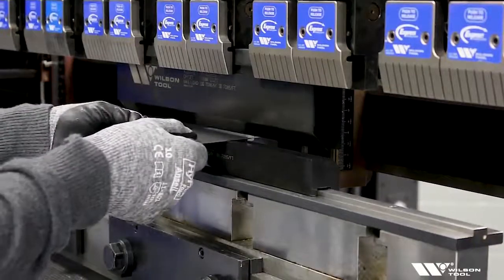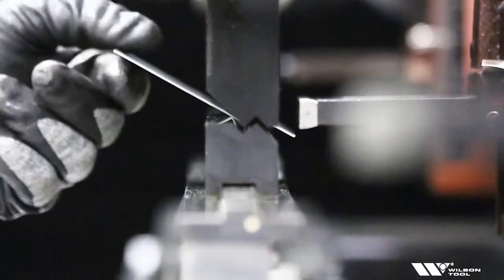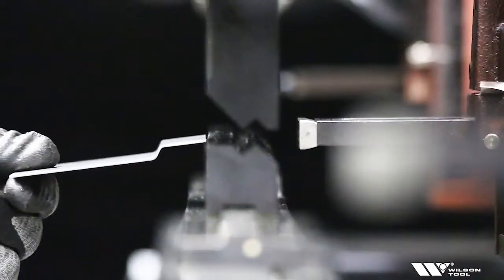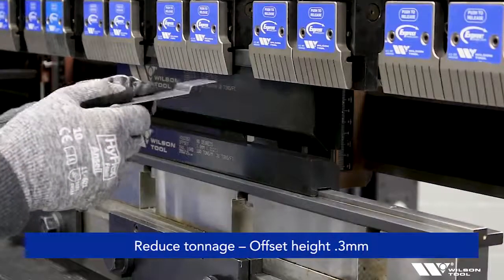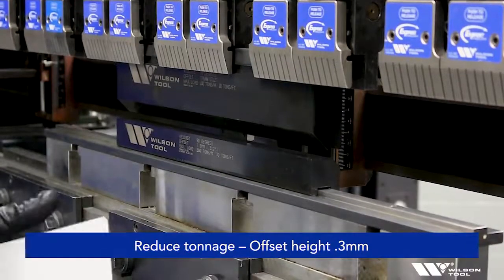And as we do, you'll see the bend is going to become more lazy. But you can also see that the plane of the material, it's parallel. So we don't have any deviation. We're happy with the height of our offset. And if you were to mate up a piece of material in between there, it would match.